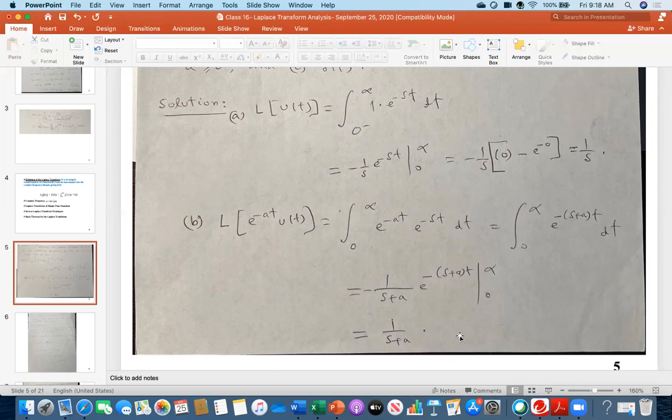The same thing, for example, you solve a circuit problem, and at the end, you have to convert back into the time domain. For example, you got some current value or voltage value for any branch based on the problem. You expressed it in S domain, but at last you have to convert back into time domain.